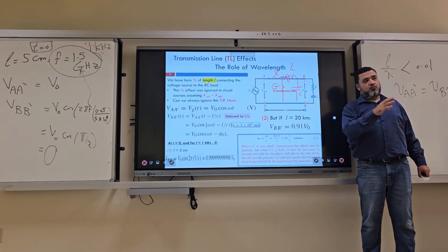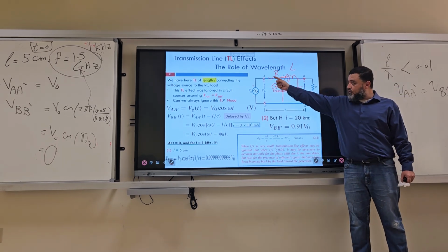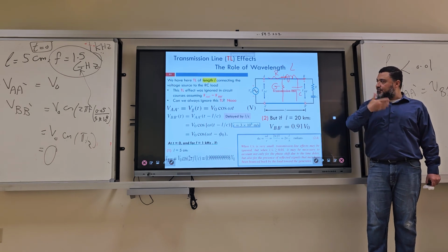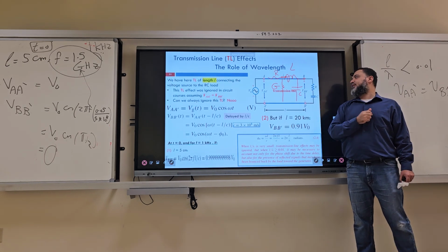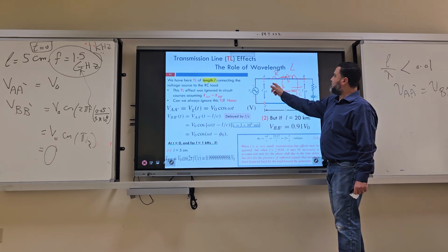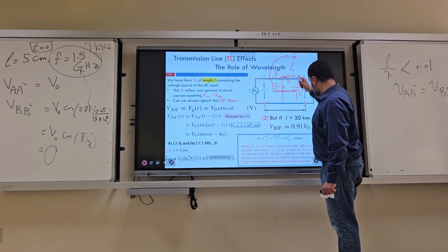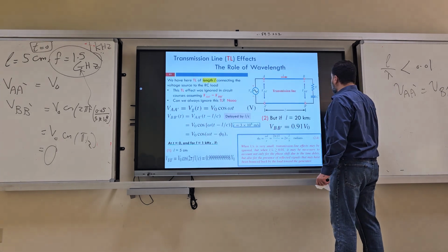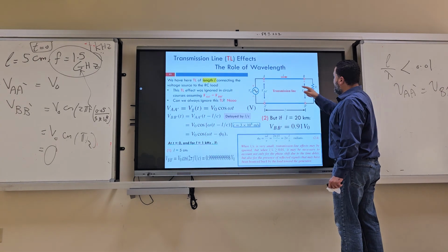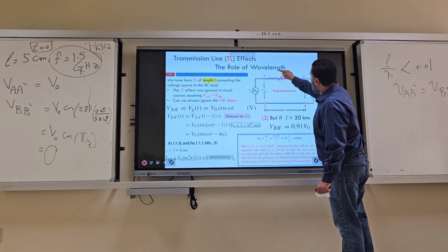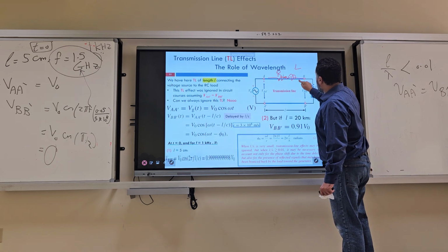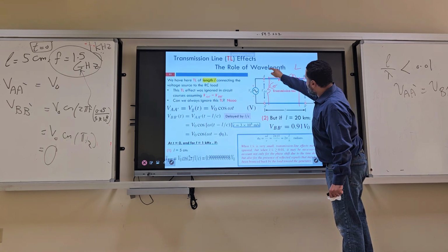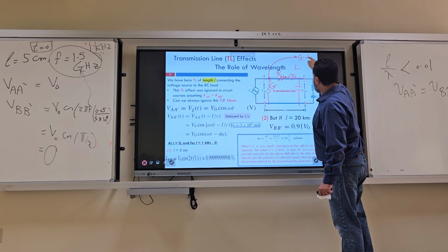Okay, so the wave will lose some of the energy over the wires and in the dielectric. This will absorb some of the energy. The more the frequency, the more the loss we have. G is proportional to, this G, guys. So again, we have R, we have L, we have C, and we have something here we call G. G of the dielectric is proportional to sigma.